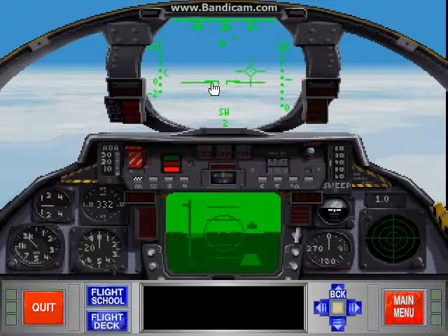The orientation of the aircraft reticle on the pitch ladder indicates your aircraft's pitch relative to the horizon. If the aircraft reticle is positioned over solid pitch lines, it means that you are pointed above the horizon. If it is positioned over dashed pitch lines, it means that you are pointed below the horizon. An aircraft reticle that is lined up with the horizon indicates that you are flying straight and level.